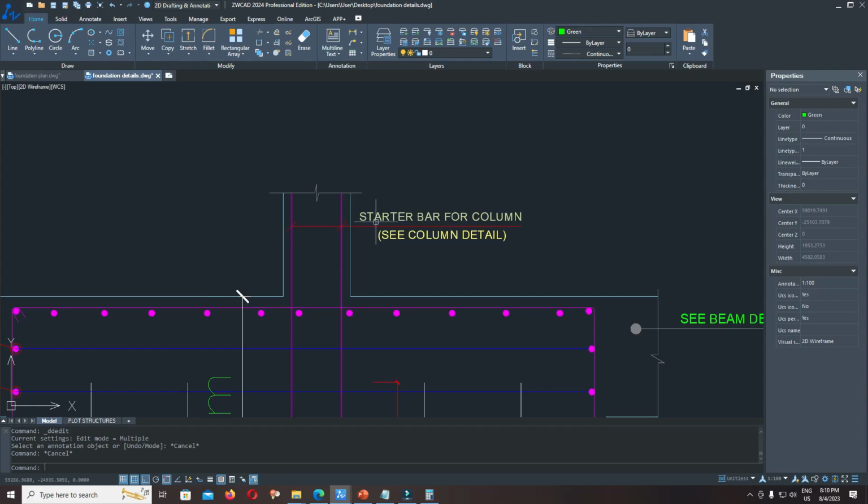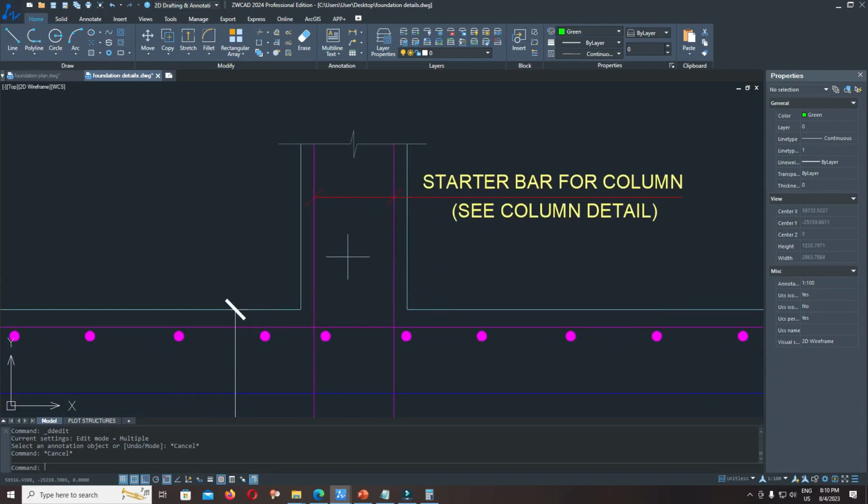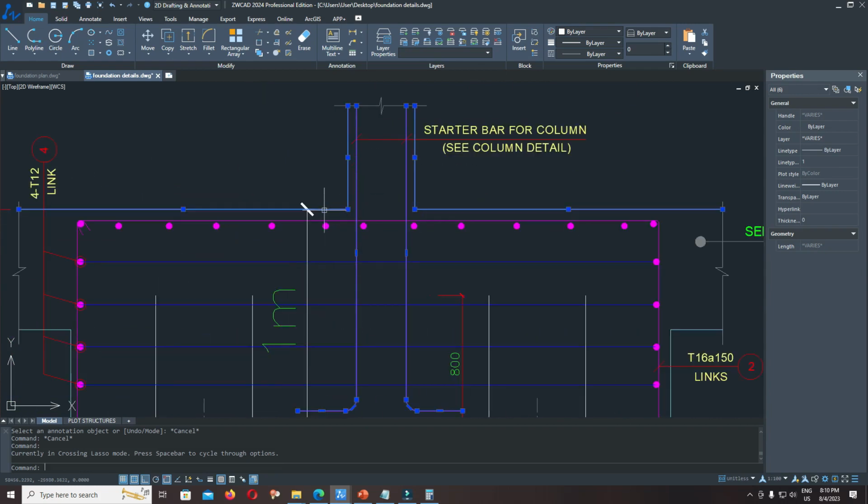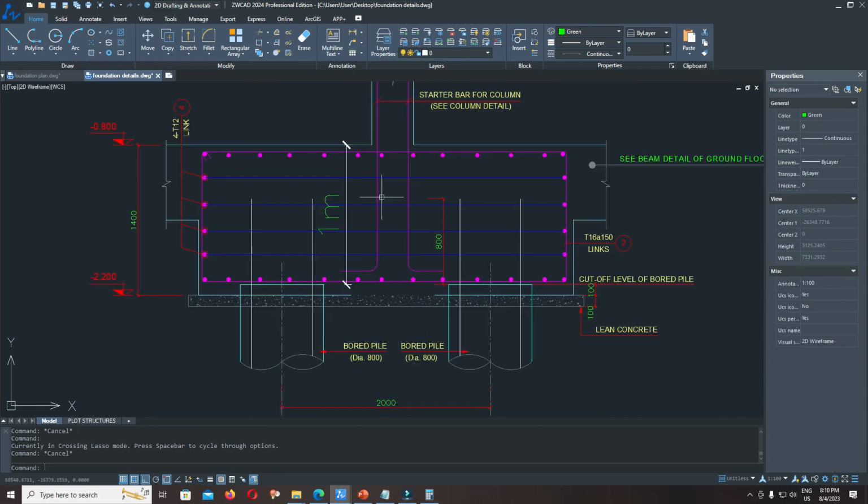Come back. This is the same as the single pile. You should verify the compressive stress at the contact area between the column and the pile cap to make sure there is no over compressive stress. And for other criteria, please check more detail in the reference document.